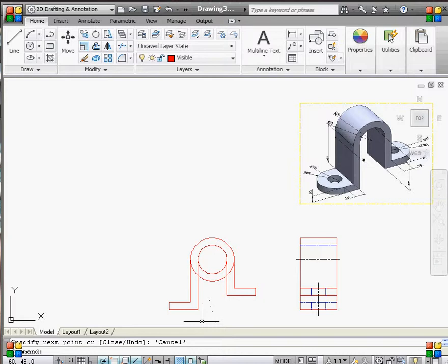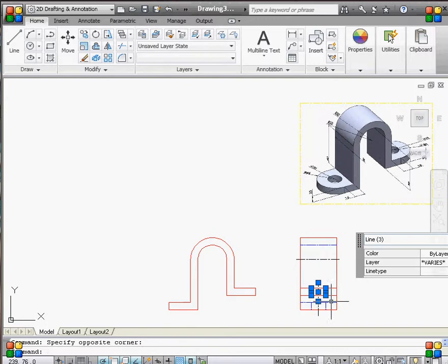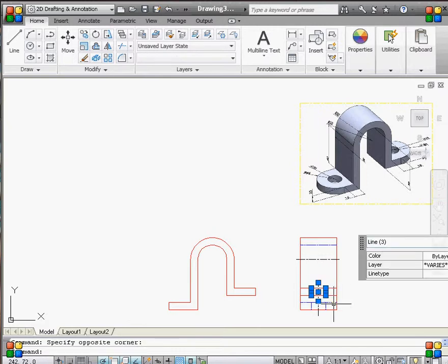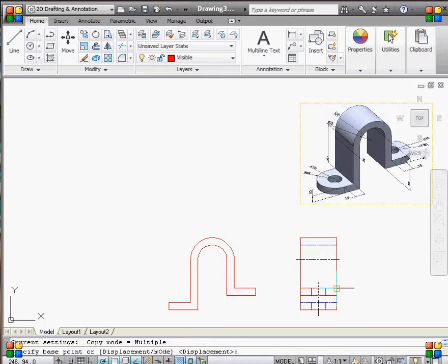So I use object tracking extensively. Now we can trim that and that. So there is our arc, and then I already have, since the hole is the same here as in here, I can just come over here, copy our hole, except for we're not quite sure where. Okay. Copy our hole, and since it's symmetric, it'll be,